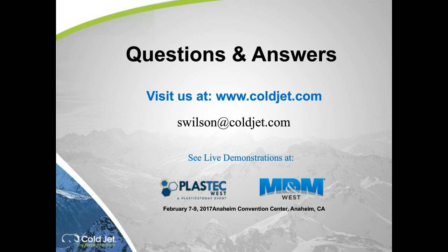If any cross-contamination is an issue, I would encourage a conversation with the dry ice company about cleaning the totes that they bring you. Totes get in some interesting environments. You're going to want to make sure, because the dry ice itself is probably going to get the green light, but the tote itself may need to be cleaned before they put that grade of ice back in it. I mean, these totes end up in foundries. They end up in a variety of environments, and the gas company picks them back up and fills them back up. On that one, I would sit down with my local gas company, tell them what my requirements are, and we need to control this process, close the loop, not just from the manufacturer of the ice itself, but the transport vessel, the totes in which they're delivered. We control that whole process.